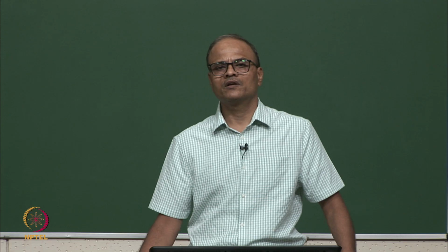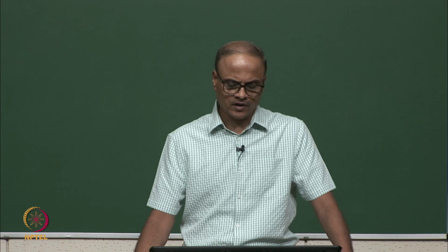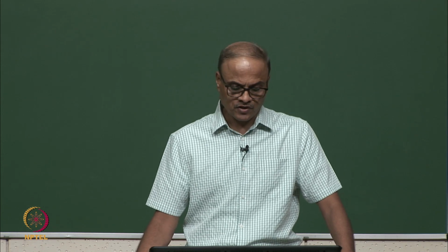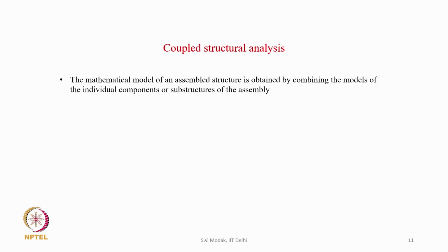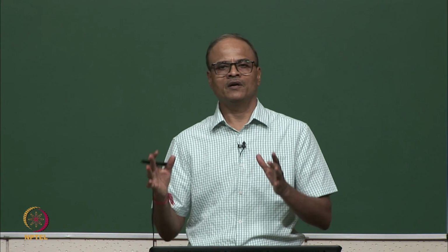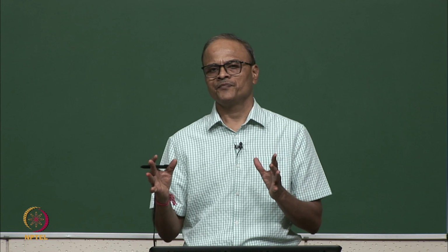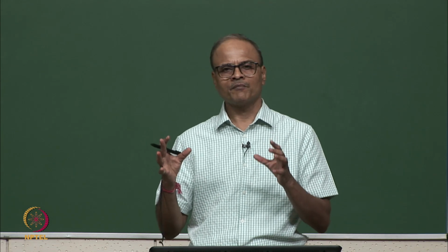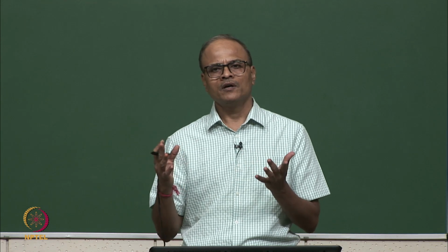Another application where the model identified through modal test can be used is in coupled structure analysis. In coupled structure analysis, the objective is to obtain the mathematical model of the assembled structure by combining the models of the individual components or substructures of the assembly. So, if there is a big structure having several components or substructures, then first the component models are made, and then the component and substructure models are combined to obtain the model of the complete assembled